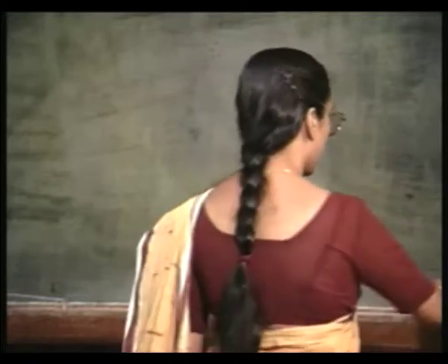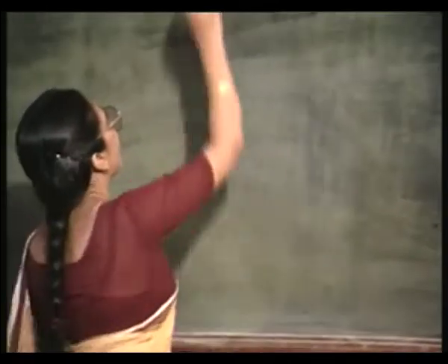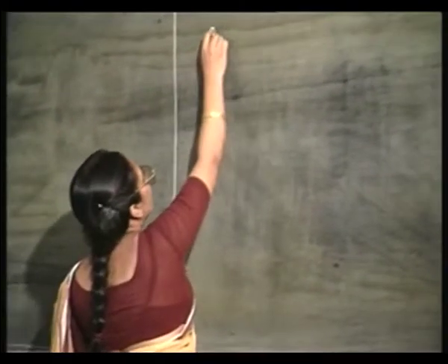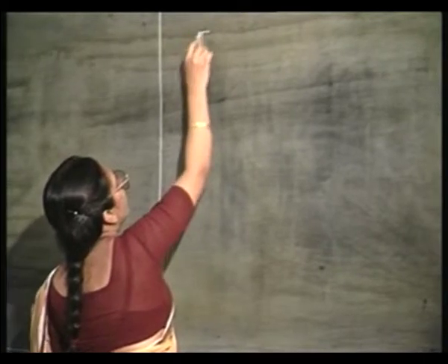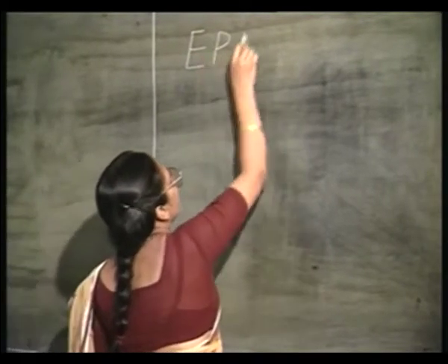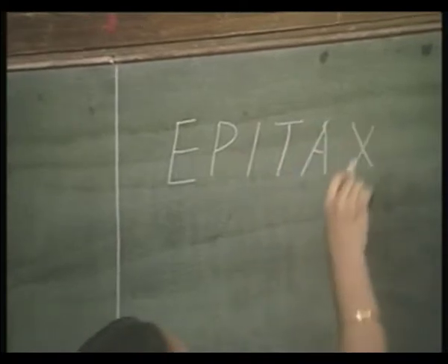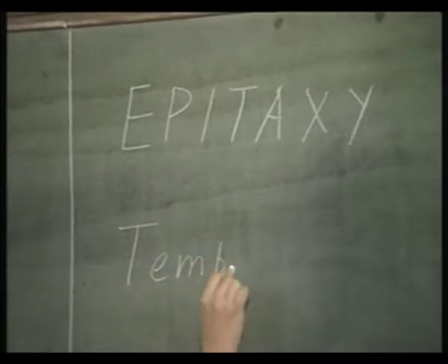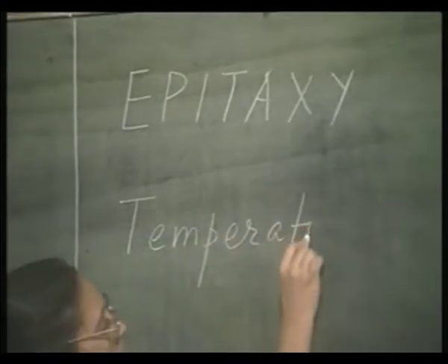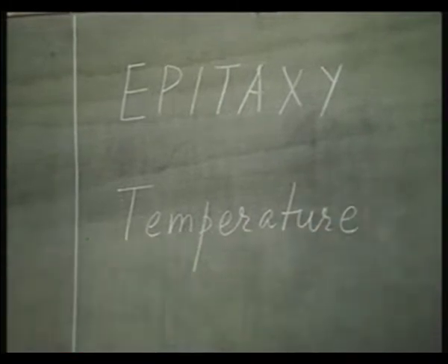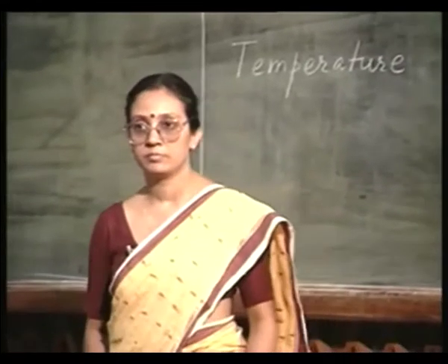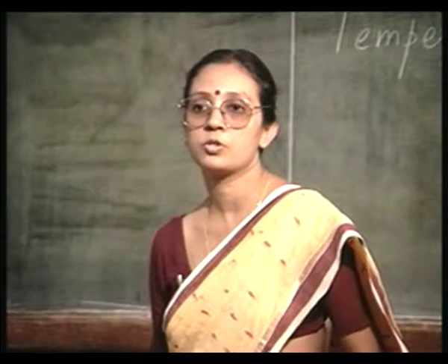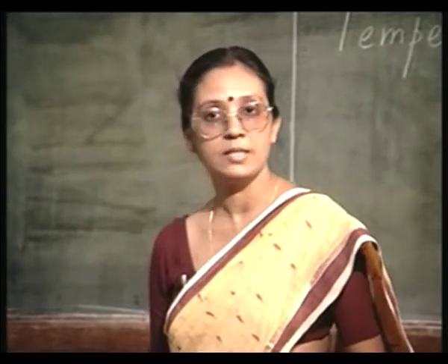So, you see, you always have to do this balancing act. So, this is one process parameter you have to carefully optimize, temperature. Higher temperature, better crystal quality, but higher temperature also means increased thermal stress and intermixing of dopants.